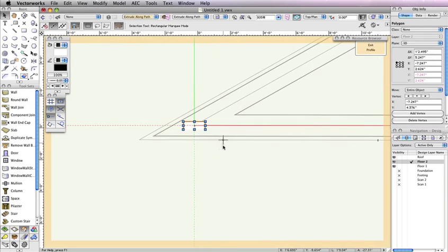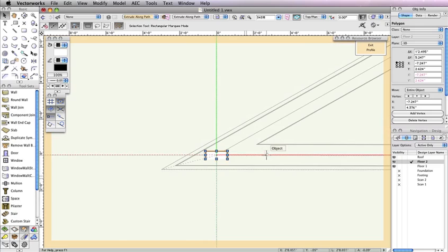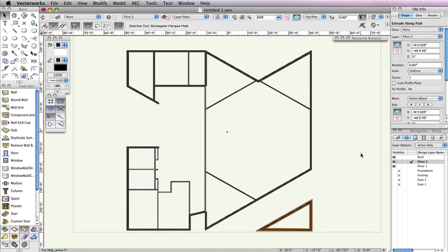So double-click the Extrude Along Path, choose to edit the profile, and click OK. Select the polygon again, and in the Object Info palette, set the top left point in the box control matrix. Additionally, set the X field to -1.25 inches and the Y field to 0.5 inches. Once complete, click Exit Profile to return to the drawing.